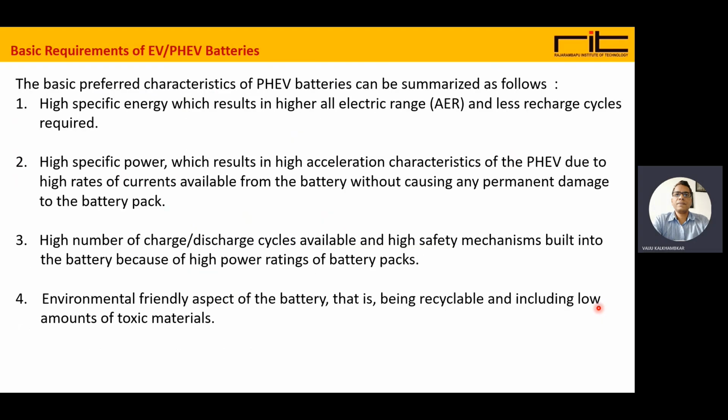The next is the basic requirements of EV and PHEV batteries. The basic preferred characteristics of plug-in hybrid electric vehicle batteries can be summarized as follows. They should have high specific energy, which results in higher all-electric range and fewer recharge cycles.